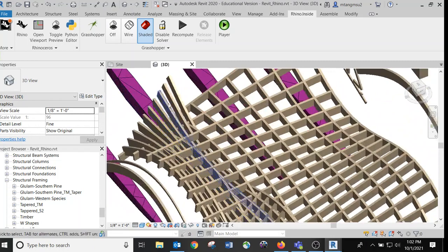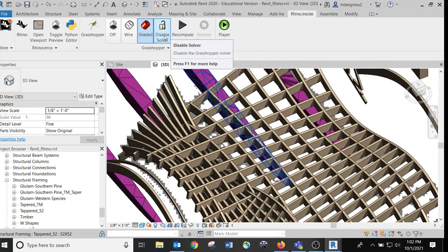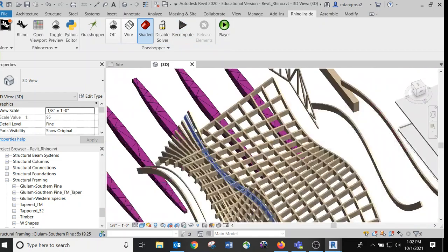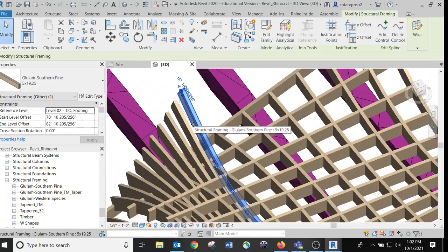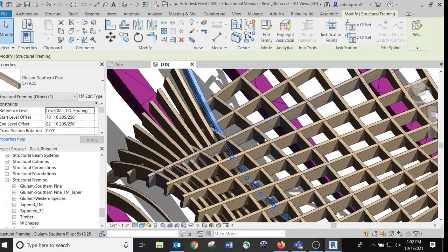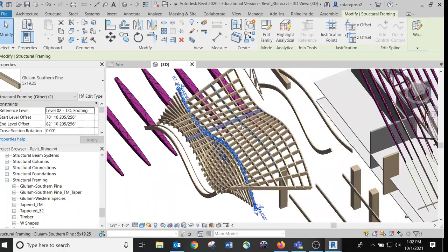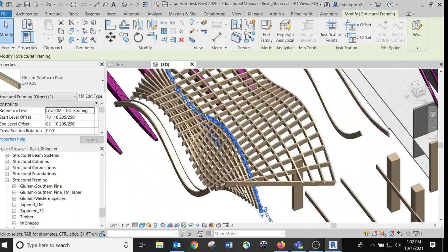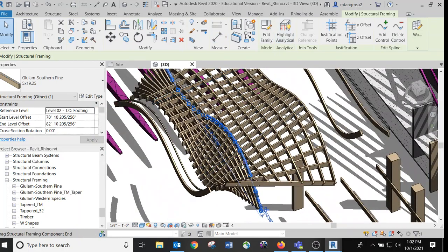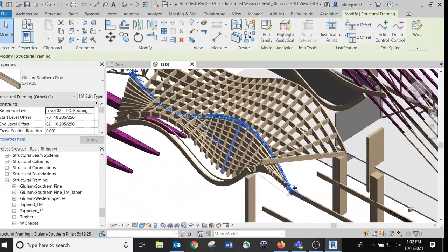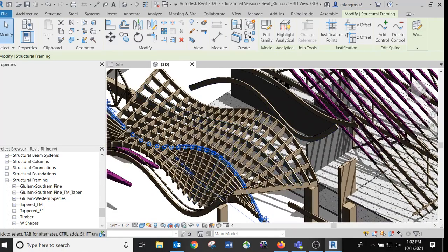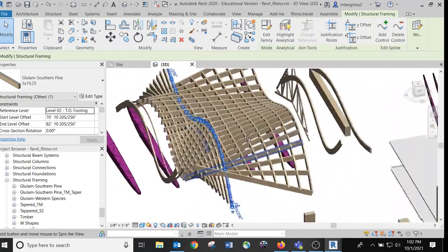But this duplicated, I would say the released version, is kind of like a bake, right? You already baked these pieces into Revit, so they do not have any connection to the original Grasshopper and Rhino anymore. So you can treat release as a sort of bake. That makes sense, right?